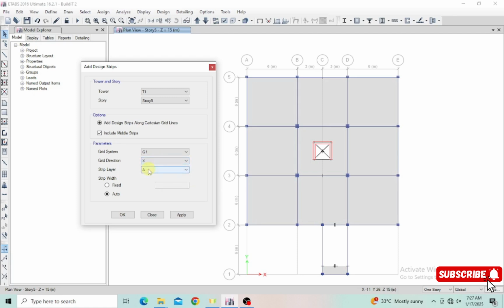So in the X direction, we are going to assign strip layer A, and with a strip width, you can input your own width of how you want the strips to be, or you can just leave it at auto calculated, and I'm going to leave it as auto calculated for the app to do that for me. So once I've selected all of these, I'm going to apply the first one, so the X. So you can see that these are the strips in my slab.